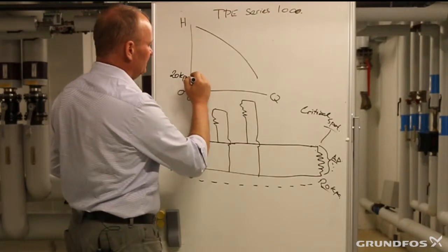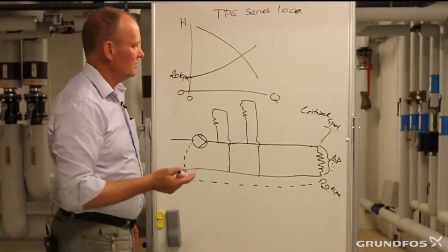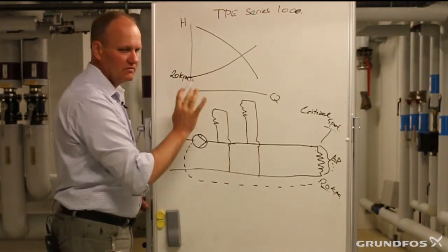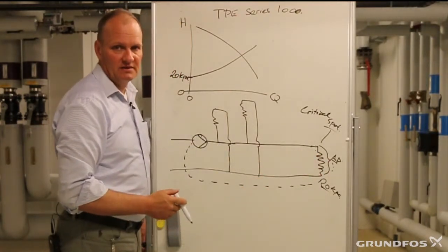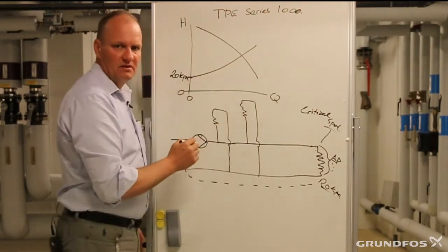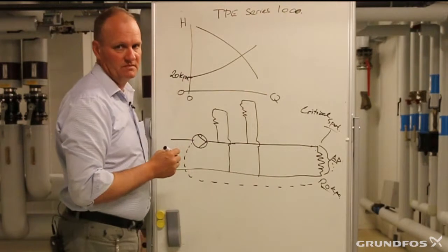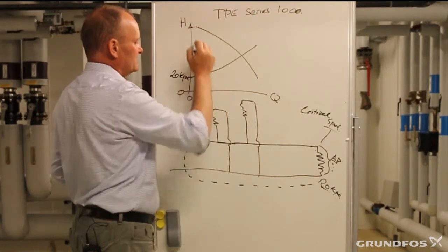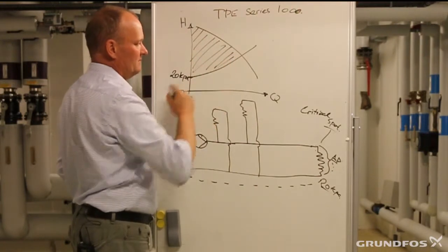And that's actually quite neat, because then it will create this square-formed control curve where we know that in reality, or in real values, we will always maintain the minimum required differential pressure on the critical point, and this pump will always compensate for the friction loss in the system and create its own system or control curve. So in this case, I would claim that it's a kind of bulletproof way to control a pump, and our savings will be absolutely maximum.